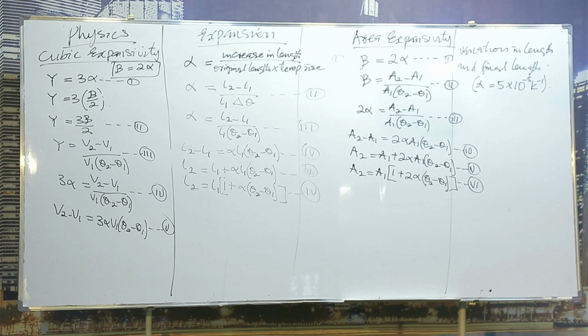Somebody asked this question, are we changing the millimeter? No. You are not changing temperatures under this because the unit is per degree, per Kelvin. So you don't change any temperature for any of the expansivities. You go by the one given to you. And you don't change the length as well. You don't change length, you don't change temperatures. That's a good question.